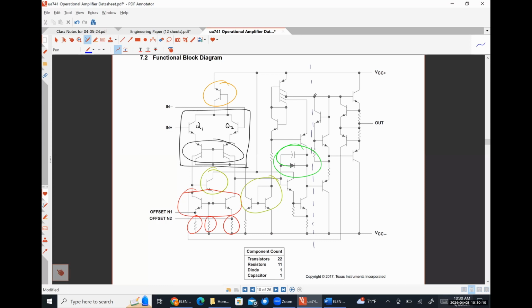So the common mode is effectively just us describing what happens when we put the same signal on both of the inputs. That is by definition a common mode signal. If the same signal is applied to both of the inputs, it is common to everything. If different signals are applied to the inputs, then we have a differential mode signal. And we can decompose literally any signal that we apply as this part is differential mode, this part is common, right?